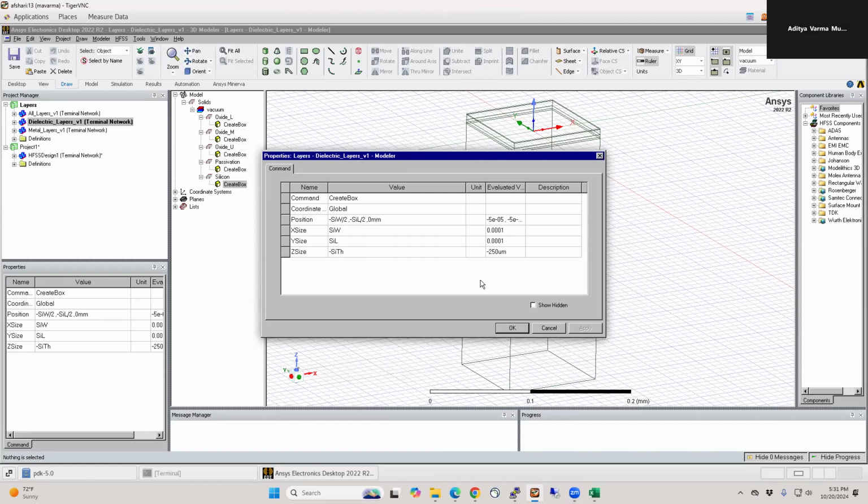For example, if you want to radiate into the silicon and then put a silicon lens on the other side, then you should know what this thickness is. But if you send an email to the PDK folks or to the foundry, they should usually tell you what this value is. It's usually around 250 microns, give or take a few hundred microns maybe.